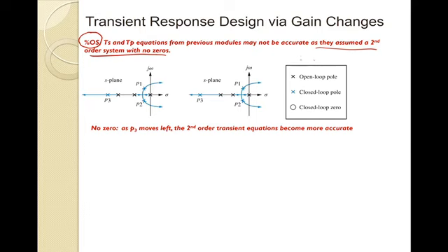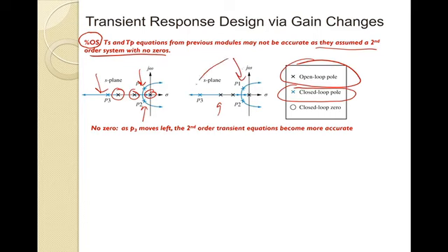Looking at the key, in black we have our open loop poles. In this case, we have an open loop pole, a second, and then a third open loop pole, and you'll see the same ones over on this side again. In blue, X, we have our closed loop poles. If we start with our open loop poles and vary our gain K, they'll migrate and go away. For a specific value of K, you might see these closed loop poles in blue as shown here.